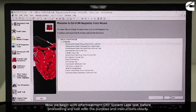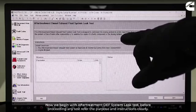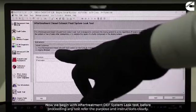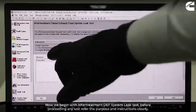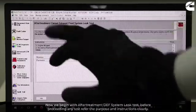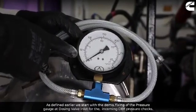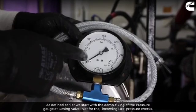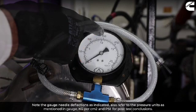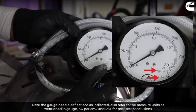Now, we begin with the after-treatment DEF system leak test. Before proceeding with any test, refer to the purpose and instructions clearly. As defined earlier, we start with the demo, fixing of the pressure gauge at the dosing valve inlet, for the incoming DEF pressure checks. Note the gauge needle deflections as indicated, also refer to the pressure units mentioned in the gauge, kg per centimeter square and psi, for post-test conclusions.